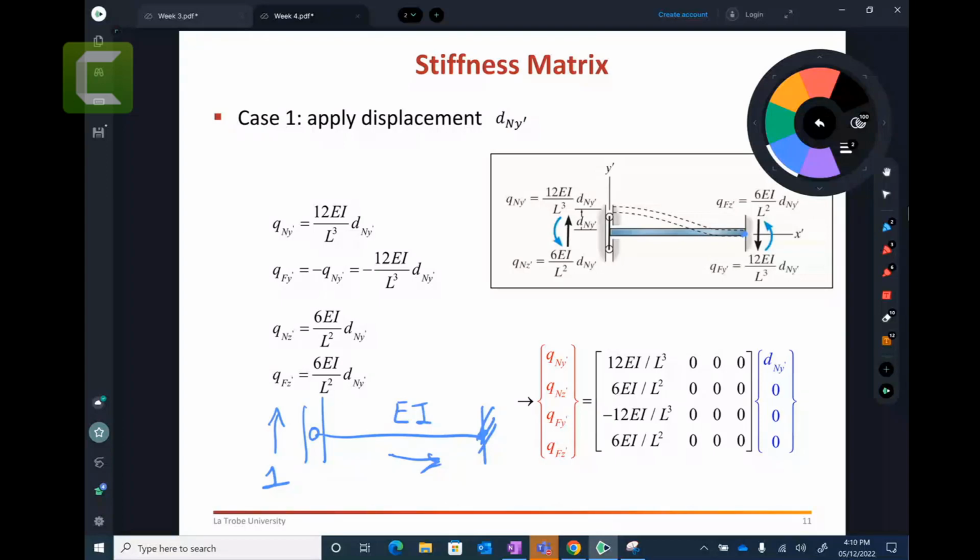You put it in a machine and you can draw the stress-strain curve, and the slope that you get is the Young modulus. It's just the measurement of how stiff the material is. How stiff meaning how stretchable the material is. So that is a Young modulus, right? Because the beam could be made of steel or concrete, or if you have electronics people, it may be made of some kind of polymer. So they have a Young modulus. Okay, it can be any value.